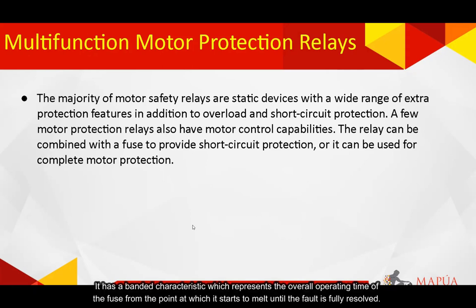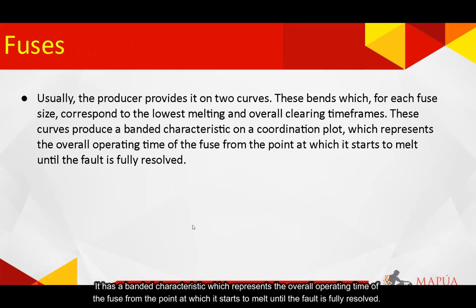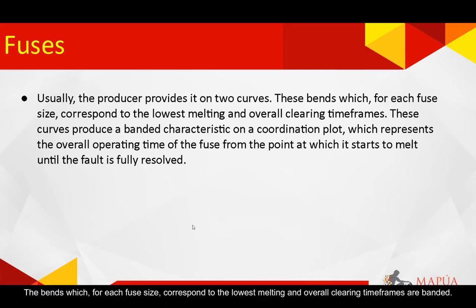motor protection. It has a banded characteristic which represents the overall operating time of the fuse from the point at which it starts to melt until the fault is fully resolved. The bands, which for each fuse size correspond to the minimum melting and total clearing time, are banded.